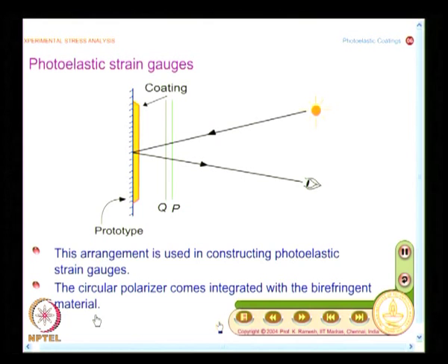So, what you have looked at now is, if I want normal incidence, what kind of optical arrangement I should think of in reflection photoelasticity. We saw that it requires a partial mirror. We said that it is bulky and also it interferes in ellipticity of polarization. So, it is not desirable to have that. So, we moved on to a commercial polariscope where we allowed a certain angle of obliqueness, without which you cannot see the reflected light. So, you have to live with that.